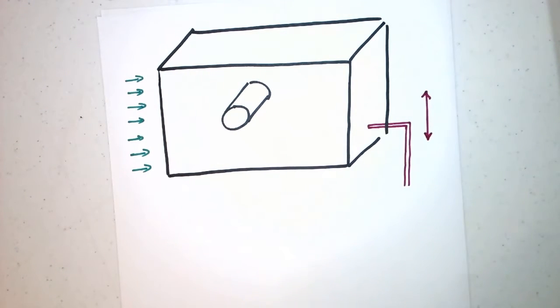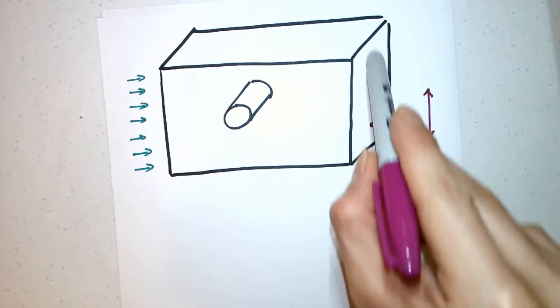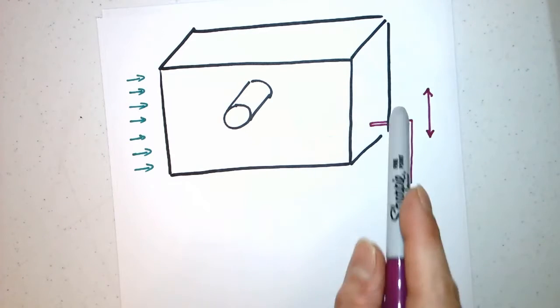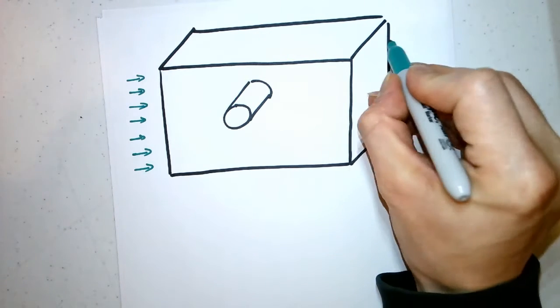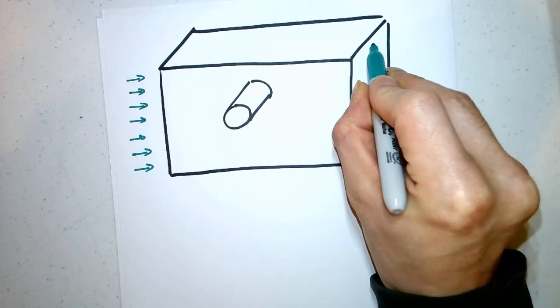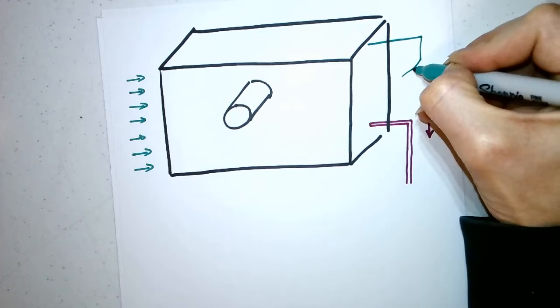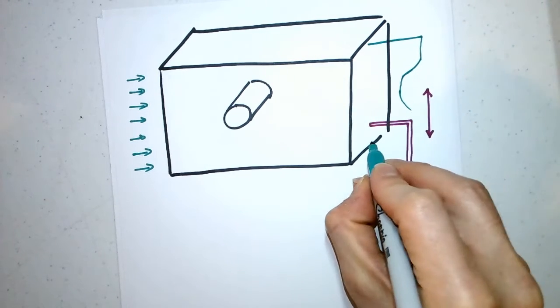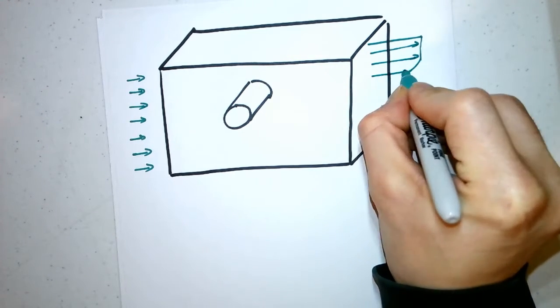The pitot tube is for pressure measurement. It's hooked up to a manometer, which we learned about in Transport 1. But we take this and we scan it up and down across this rectangular prism, and we measure the velocity downstream of this object. And so that velocity profile might look like, say, a high velocity that actually reduces in the wake of this object, that might return to a higher velocity. And so the vectors that we draw might look something like this.